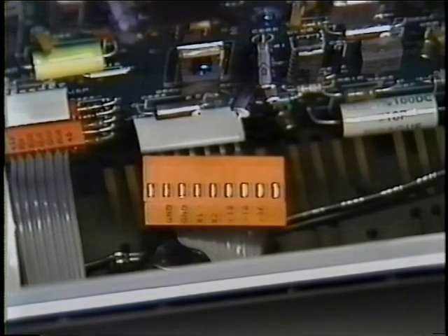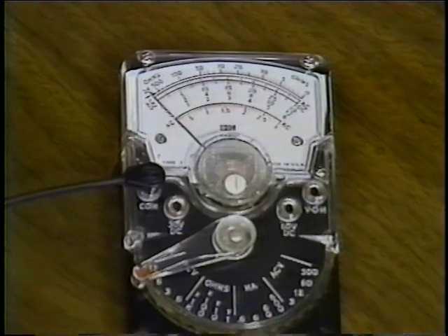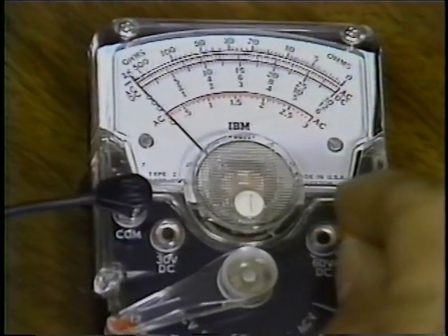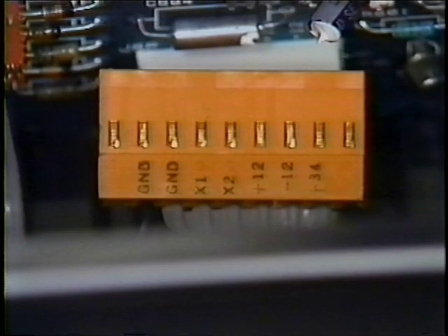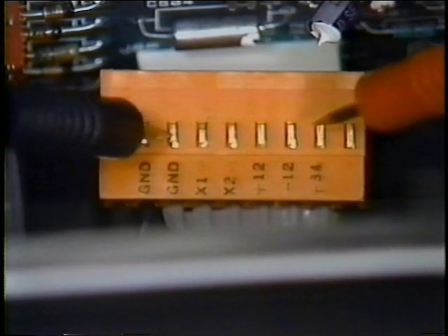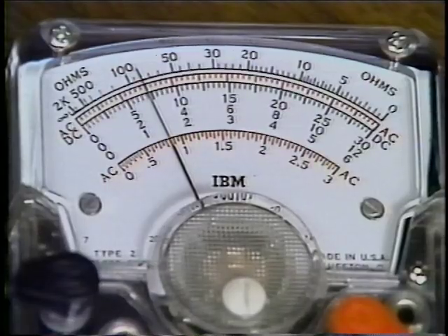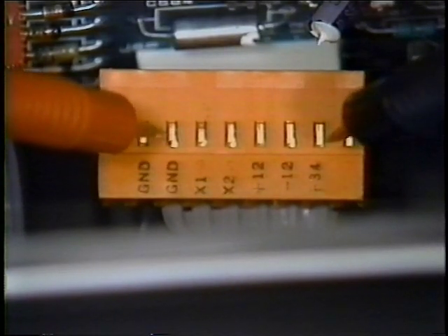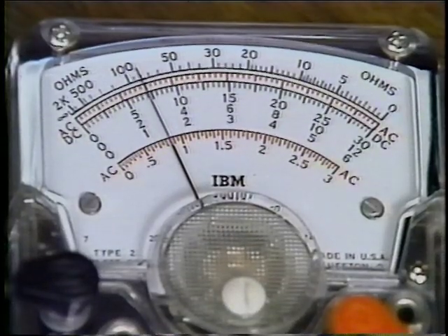To read these voltages, set the meter on the 60-volt DC scale, then turn the machine on. When taking power supply readings with the power supply connector J6P disconnected, you must use the power supply ground on pin 2 of the J6P connector. The reading from power supply ground to the plus 12-volt pin should read from 6 to 18 volts DC. To measure the minus 12-volt pin, reverse the leads to read negative voltage. You should read from minus 6 volts to minus 18 volts DC.